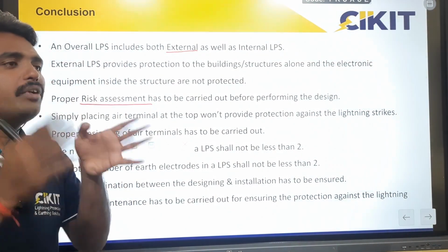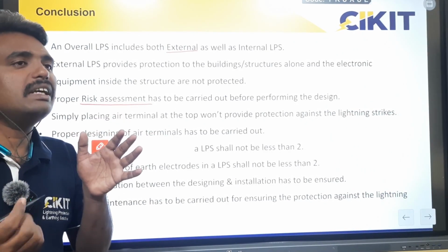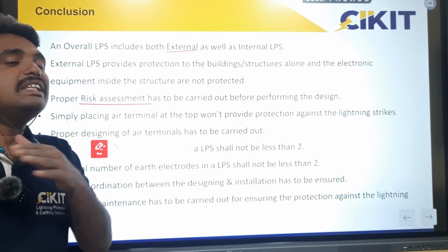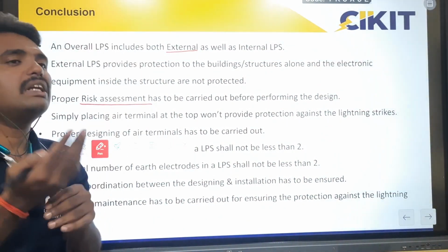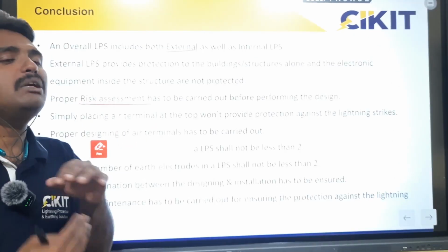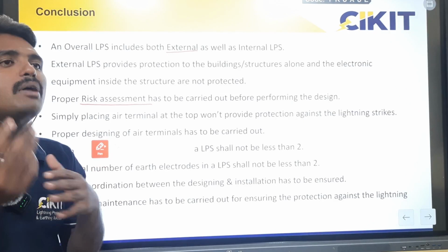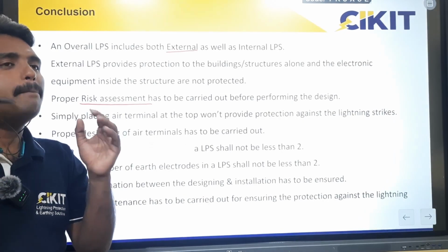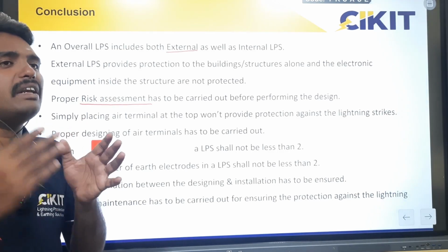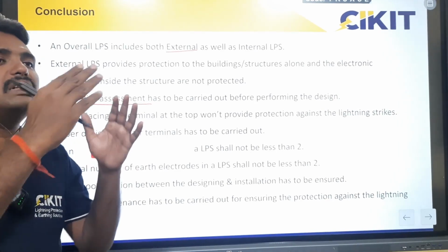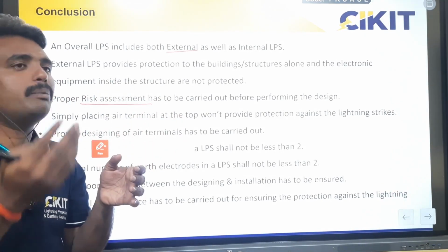side flashing. For buildings with height of more than 60 meters, the probability of lightning striking the side of the building rather than the top will be a little higher. So we need to provide additional protection measures for buildings greater than 60 meters. We are planning to organize one more webinar mainly concentrating on the risk due to lightning on high-rise buildings. We will explain the design parameters specific to high-rise buildings in that session.